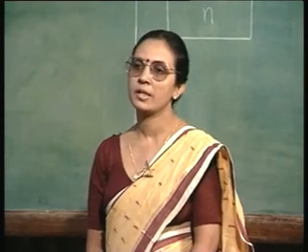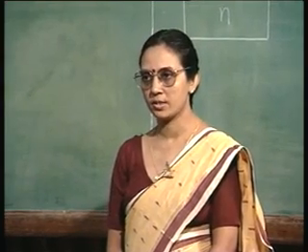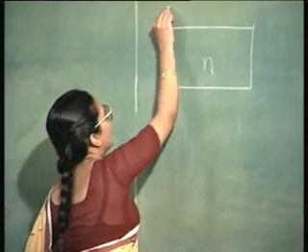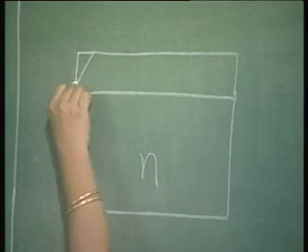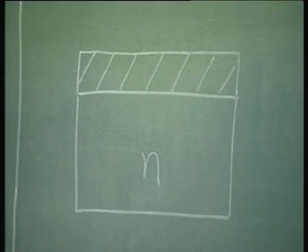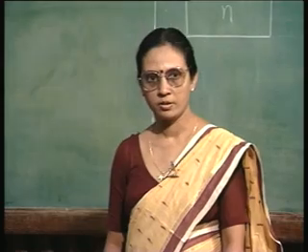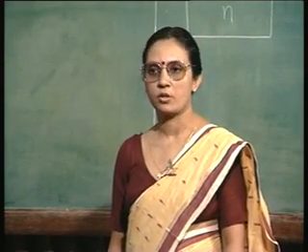First step is identical to what we have done even for a bipolar junction transistor, that is you grow an oxide. This step is called the field oxidation. You can see in the card it is written as the field oxide.